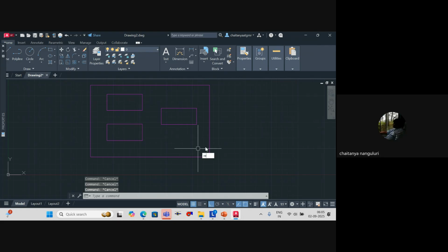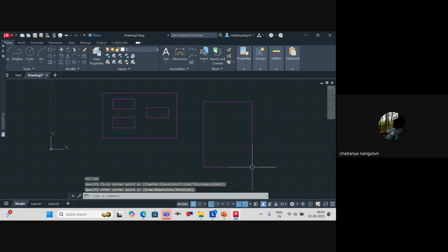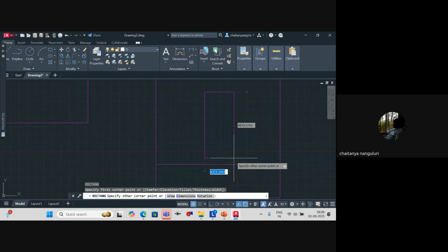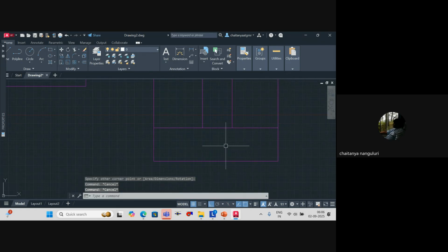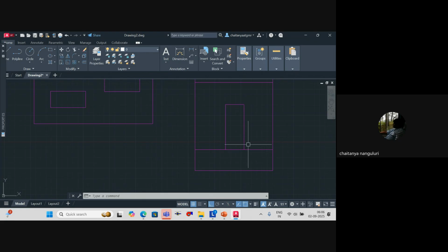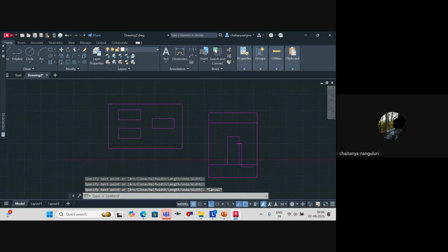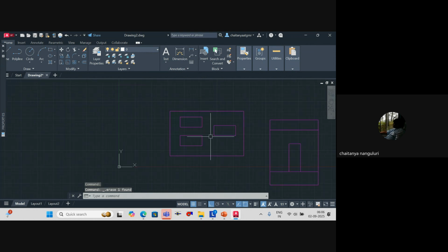In the case when you have a lot of cables, architecturally, what we do is, let's say this is your civil structure. You have one ceiling like this, one floor like this. Over this, you have your rack, so that all the cables will go underneath this particular one. Directly it gets connected, and from here it will come out and then get terminated to your server. So a bunch of cables can enter like this. Understood? So that when you have multiple server racks, people can easily walk around this one and access the servers. So in those cases also we go for floor grills.